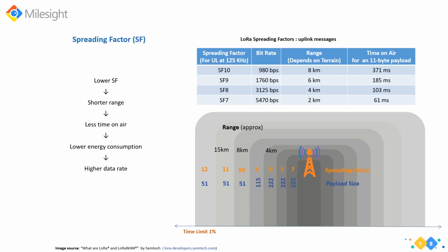For short range communication, speaking rapidly, it can pass more data at a higher data rate, as opposed to the distance extremes. So here you can find that a higher spreading factor means a smaller payload size. And this trade-off of distance against power transmitted and the quantity of data sent is covered by the data rate that ranges from 0 to 6, so 0 at the extreme and 6 nearby.